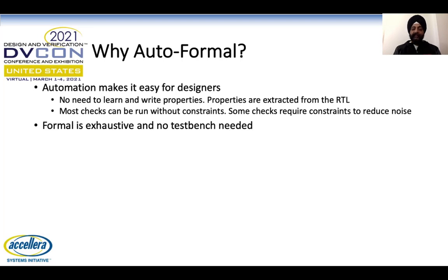And why formal? Formal is very exhaustive. That is one, and it does not require any test bench to begin. So that is the other part. So you can get started with formal much earlier than what you can do in the other verification techniques, where some development of test bench is required before you get started.